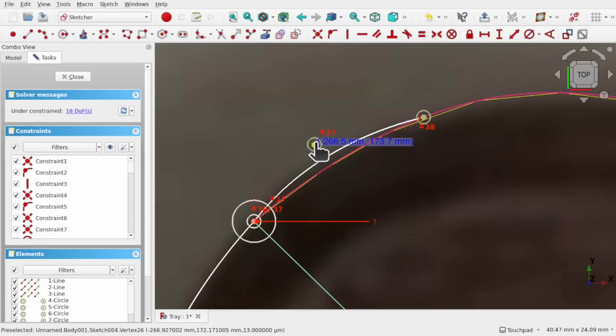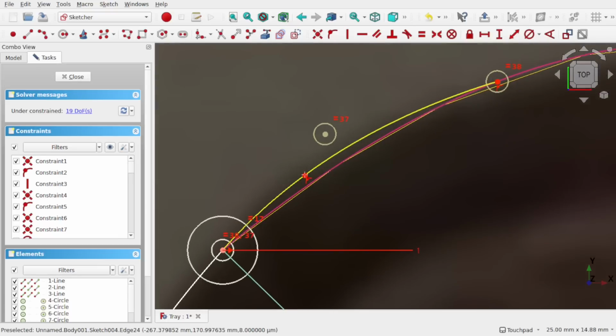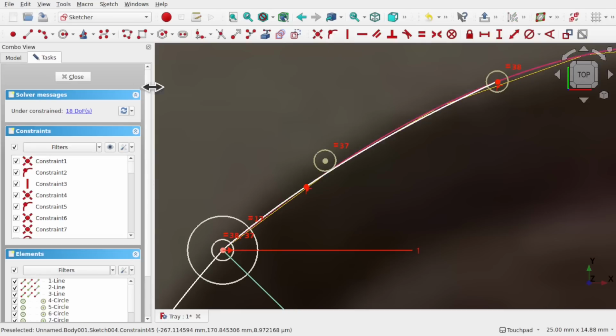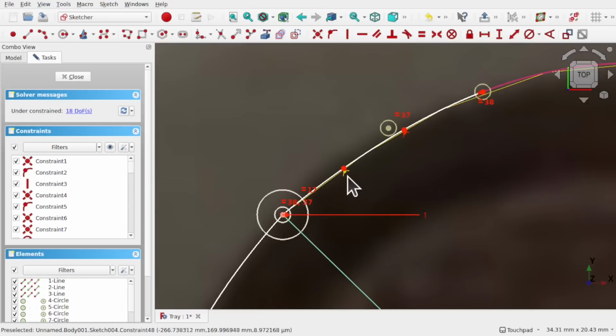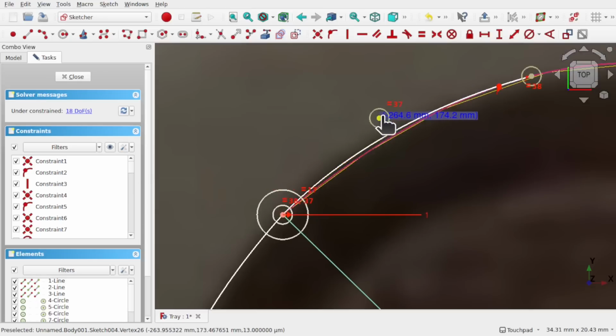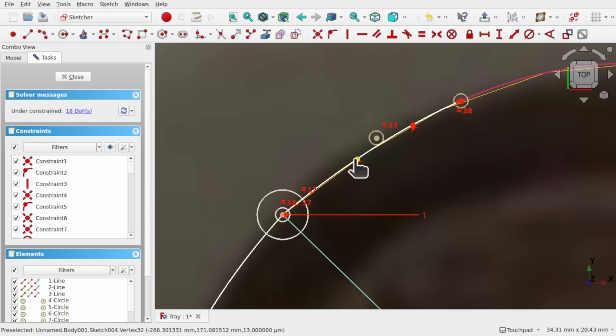To do this, what we can do is utilize the points. So I'm going to click on the point, attach the point to this curve here, hit escape, and take this point and this B-spline point on object constraint, and add another one, say to here, this point, and take this point and this B-spline point on object constraint. So we've constrained that to that line there, and you can see they're pretty locked in. Start moving this back and forth. So we've got a reference to the curvature here. Let's tighten this up a bit and bring this back here.